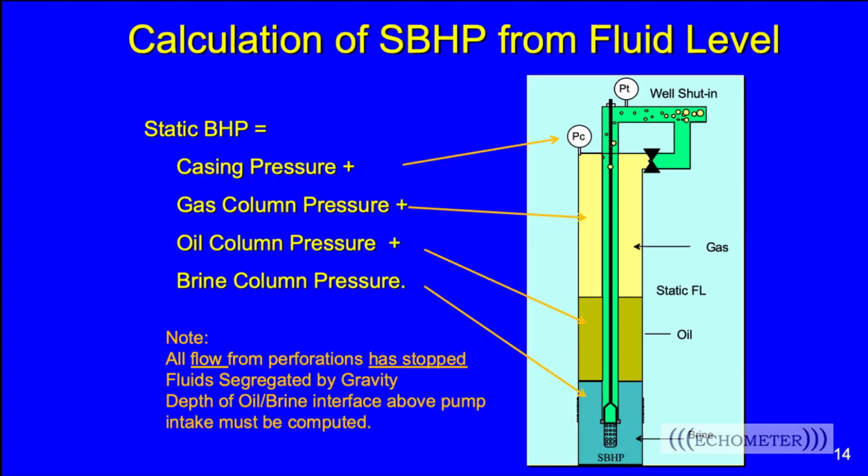Some people will say, I don't know how long this well has to be shut in to obtain the static bottom hole pressure. How long does it take to static out? Well, in that case, just come out there and shoot that fluid level every few days. And when you see that it stops changing, then you know you're staticed out.